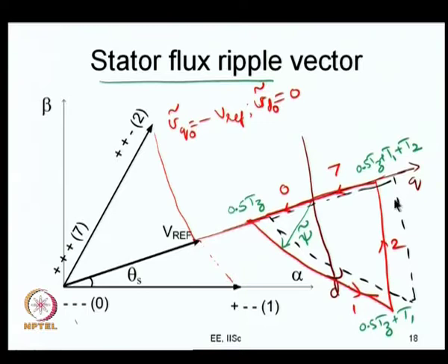What happens is, it becomes very close to conventional space vector PWM. The division of null vector time is almost equal, and therefore, you get the same thing as the red one. That is the reason why when you have a third harmonic injection whose amplitude is 1/4 of the fundamental, your THD is minimized, but that is not the case when, let us say, you have 1/6 or some other third harmonic, when the percentage of third harmonic added is something other than 25%.